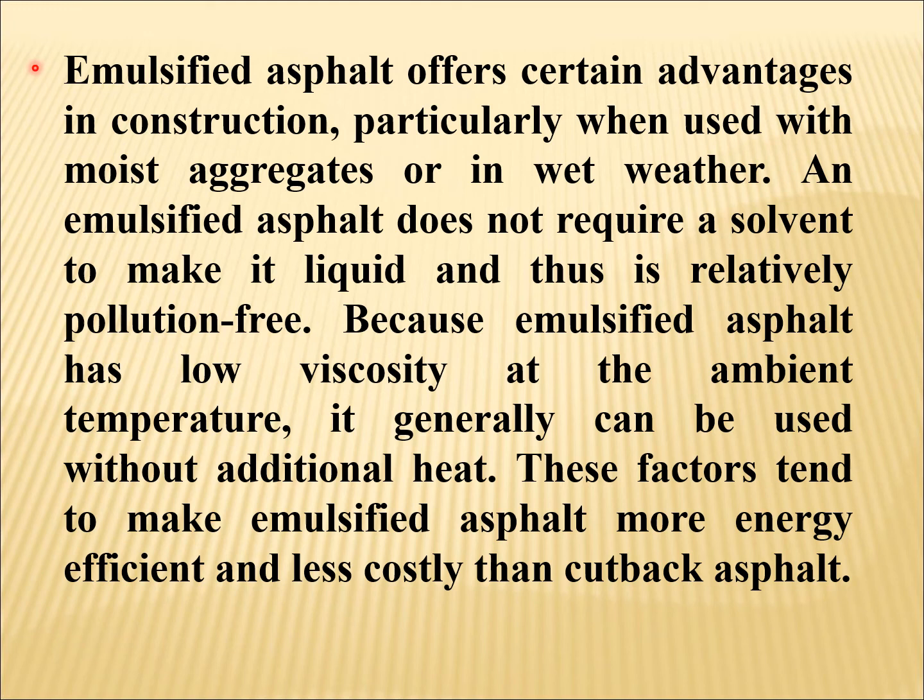Emulsified asphalt offers certain advantages in construction, particularly when used with moist aggregate or in wet weather. An emulsified asphalt does not require a solvent to make it liquid and thus is relatively pollution-free. Because emulsified asphalt has low viscosity at the ambient temperature, it generally can be used without additional heat. These factors tend to make emulsified asphalt more energy efficient and less costly than cutback asphalt.